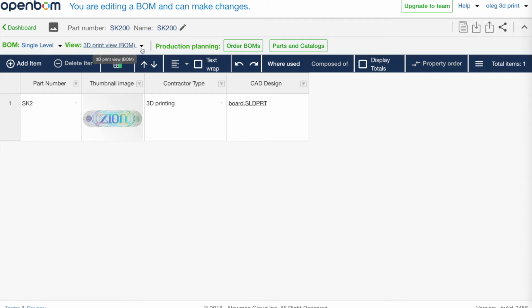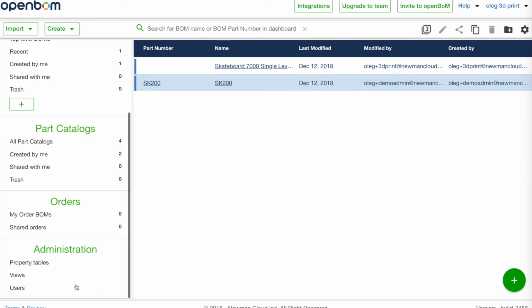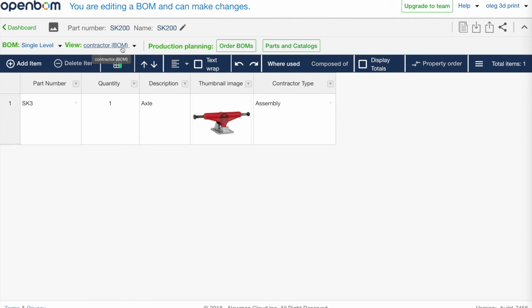So to repeat what we just did: I created a BOM with a very specific configuration of the view that can restrict other users to see information in this view, with a limited number of columns, and also a limited number of rows based on the filter. Then I created the user, and I configured this user to get access with restricted views. And when I get to this user, I can only get access to this particular view and not anything else.